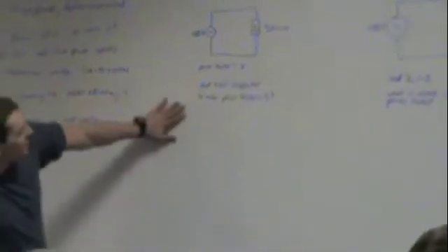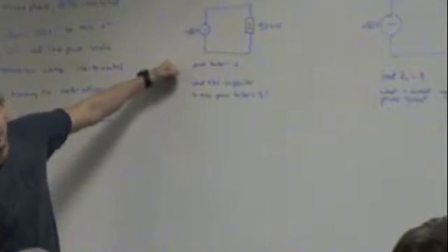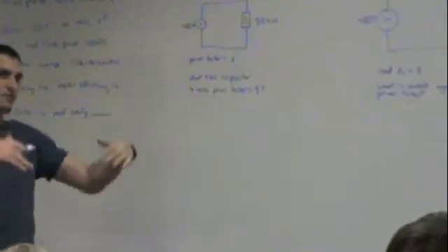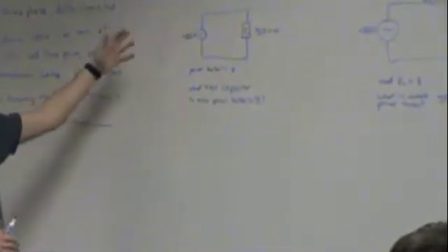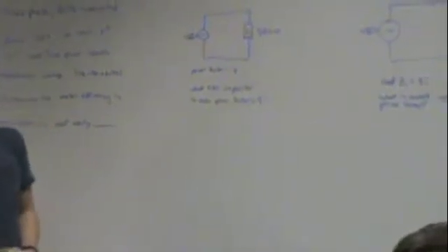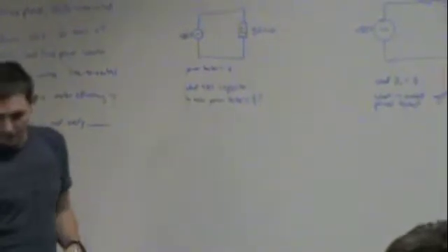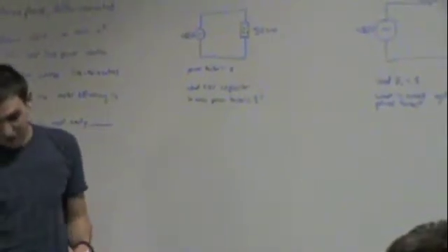Okay, so what we need to do is we have the reactive power causing the power factor problem. So we need to reduce the reactive power by including a capacitor in the circuit. Maybe this is sounding familiar to people, maybe not. So we're trying to counteract the power from the inductor and align the phases a little better to 0.9. We do that with capacitors, if you remember. So I drew the power triangle, Jeremy drew the power triangle again.